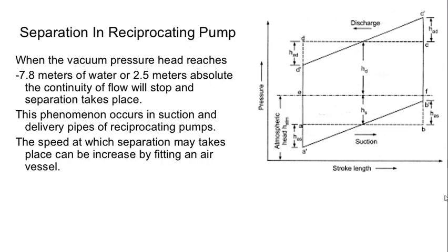This is another lecture on reciprocating pump. In this lecture we will discuss separation in reciprocating pump. First of all, what is separation? When the vacuum pressure or pressure head inside the cylinder reaches the vapor pressure of the liquid, then the continuity of flow will stop and separation takes place.